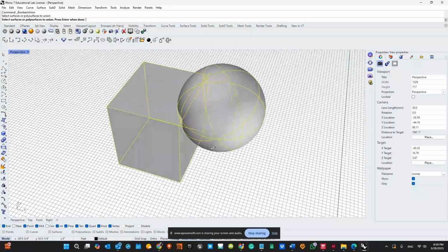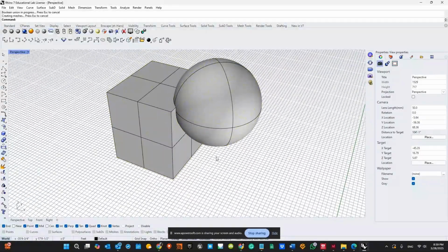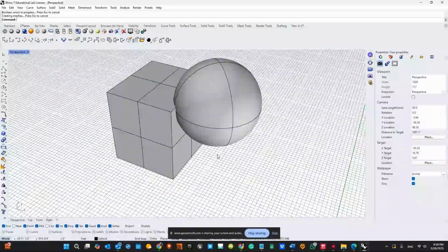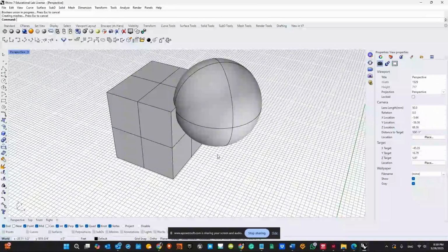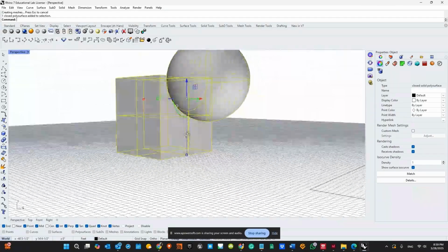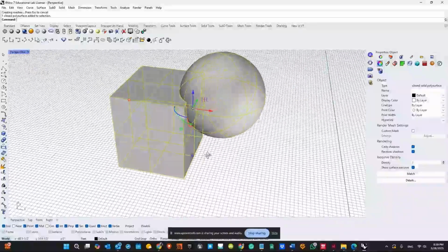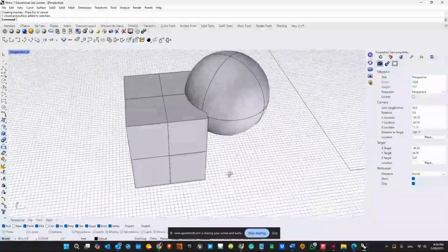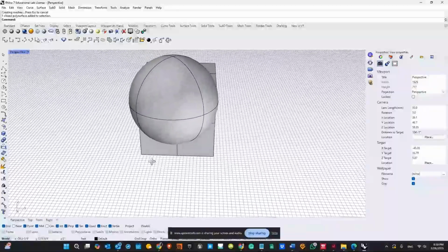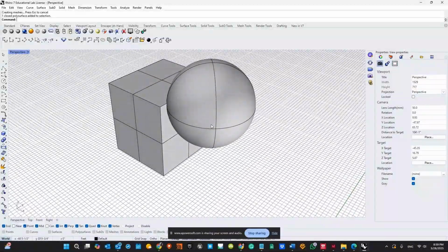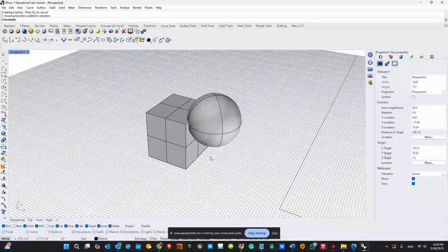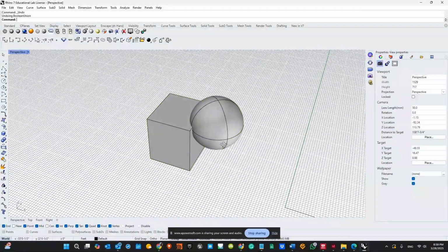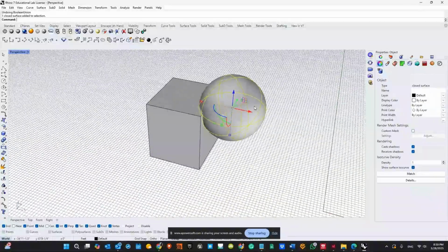And in this one, I'm gonna just hit OK, enter, and you see that right now we'll merge them into one shape. The two objects are now combined as a single volume, right? So when I click on that, you see that both of them are selected, and I have one object. It's really interesting, and you can play with that and create new complex geometry.